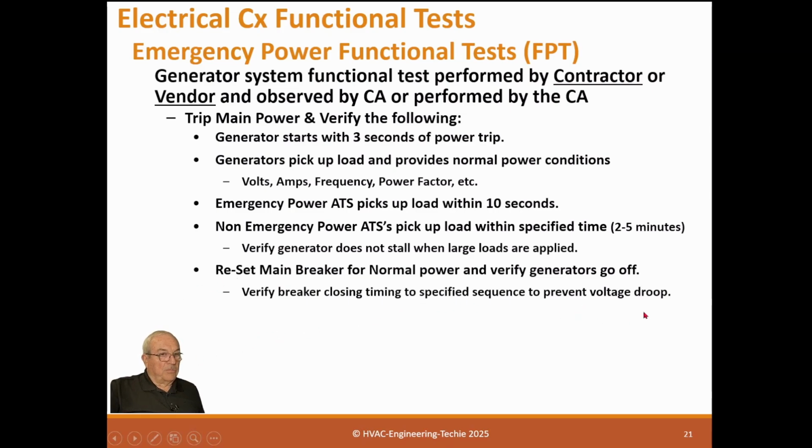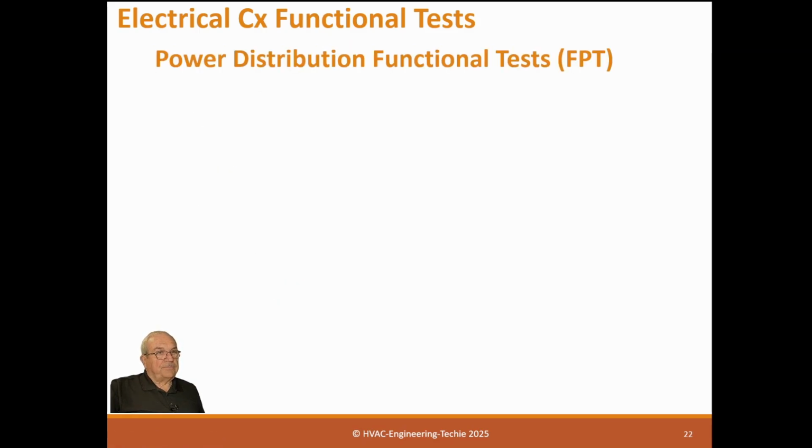Same thing, so we don't provide voltage droop. Verify the generator cool-down time before it shuts down. So normally it has a 5-minute cool-down period. Might be longer depending on the generator manufacturer, but you want to verify that.